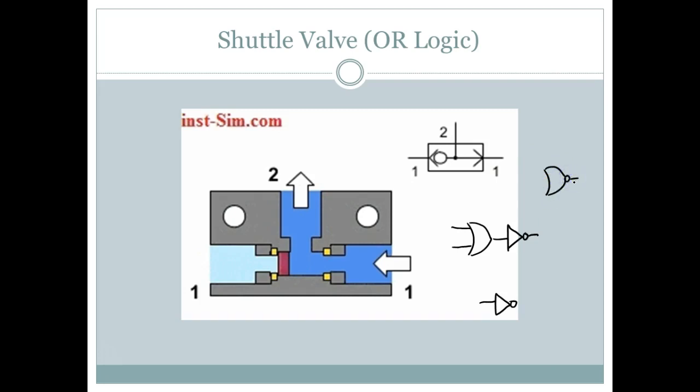So what I can do is take my shuttle valve. Y'all understand this? And then I can run it into a second valve, and this would be a pilot operated valve. Okay. And then we'd have a normally open valve, and over here, this would be closed. And then my pressure comes right here.